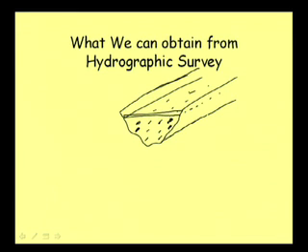Then sometimes we keep on moving while measuring, and then we need to make a lot of corrections in those measurements, because there will be a speed of the boat also. So, anyway, by some means we can measure the velocity at this point. Then we have observed that in this vertical section we are getting some velocity, and when we plot this, again on the surface also we can measure velocity.